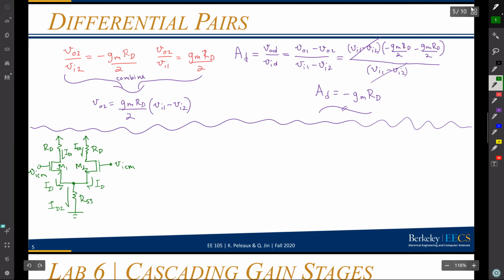So if I have this circuit, I can actually redraw it. And this might make some people uncomfortable, but for now, trust me that this is allowed. And I'll explain why if you have more questions. So what I'm doing is I'm splitting this source resistance into two source resistances in parallel. If I combine these two in parallel, they need to equal RSS. So that tells me that each of them is going to equal 2 RSS, because then when I combine them in parallel, I'll get half of that value, and I'll get a total that's just equal to RSS.